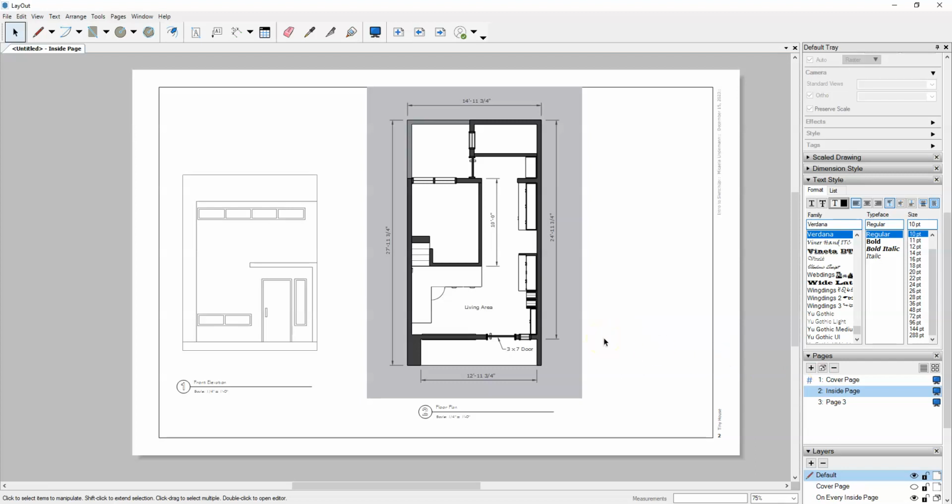And then just like we talked about, most options for customizing your view, like turning on and off different tags, your different layers, choosing what sections are active, your styles, all of that should be controlled through SketchUp rather than layout. And then we also talked about, although there are drawing tools in layout, your drawing elements that are not your annotations, like we just made this view title, should mainly be used in or drawn in SketchUp.